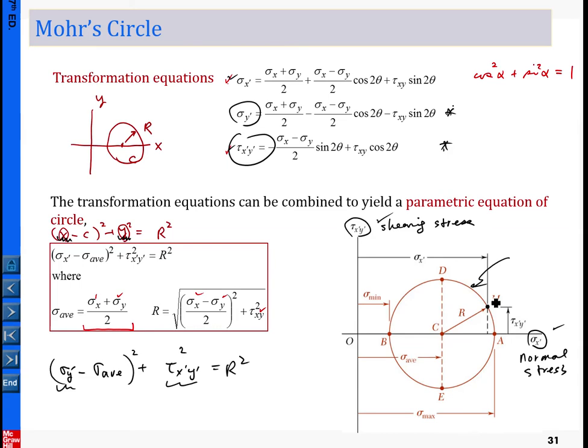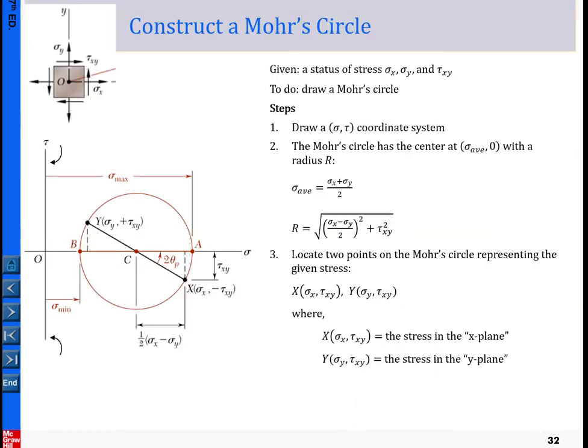Mohr circle is then simply a very concise, integrated description of the three equations in a particular coordinate system. What kind of coordinate system? The normal stress axis integrated with the shear stress axis. Keep that in mind, then we begin to exercise how to construct a Mohr circle.